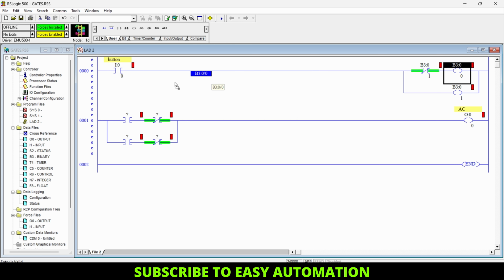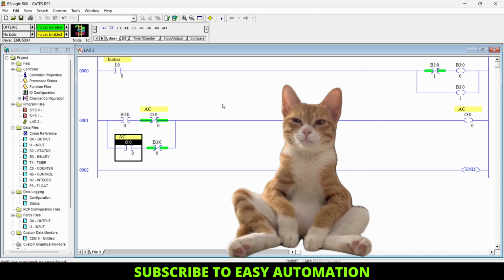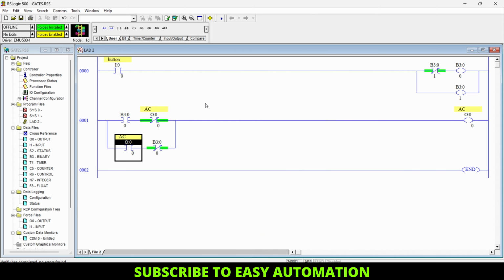I will copy this trigger pulse bit address to our NO contact of the second rung, and copy this one here for the NC contact as well. For this NC contact we need to copy the output coil's address, and for this NO contact as well we need this address. So this is the total program for the remote function. Yes, this much only, no complexities, but the actual thing happens when we run this program.